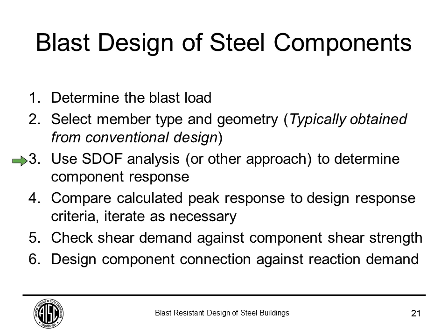Once you have calculated the response of your component, you're going to compare that to the response limits, which are generally expressed in terms of support rotation and ductility ratio. That takes care of your flexural response.